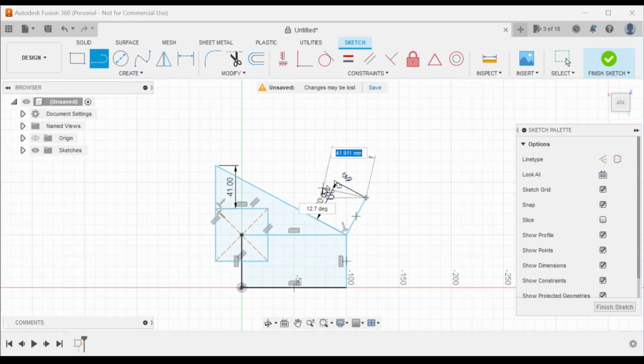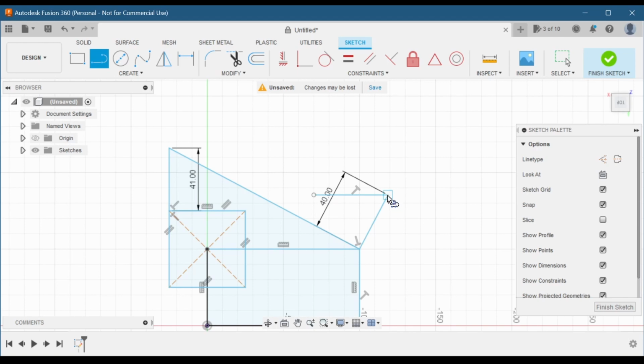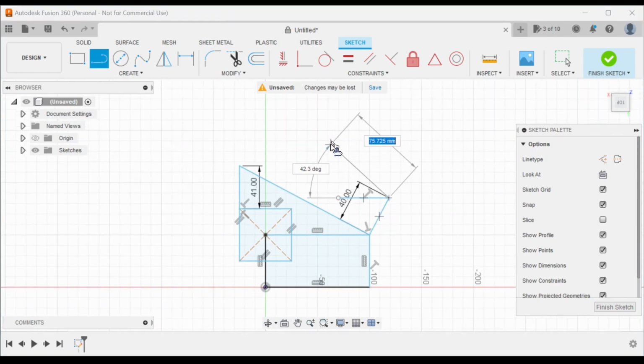So it's quite cool. And let's say we want some kind of baseline to help us construct triangles better. We can use the line tool to make that, and then we make another line. Now the reference angle is based off of this line that we drew. Let's say the angle is 30 degrees. You use tab to move between two numbers, so I press tab to move and change this to 30 degrees. Once you do that, it locks down that number. The mouse can no longer influence it. Even if I pull it off to the side, it doesn't do anything unless I pull it below here, where it's just 30 degrees, but under the line rather than over.